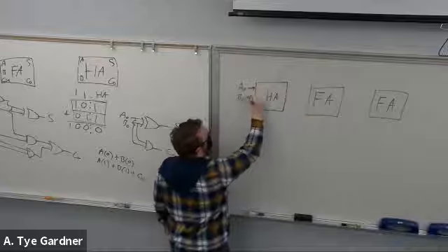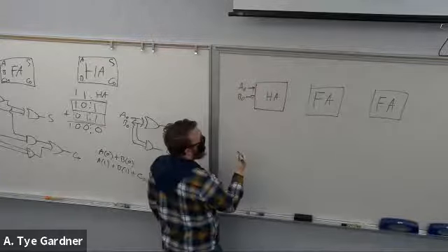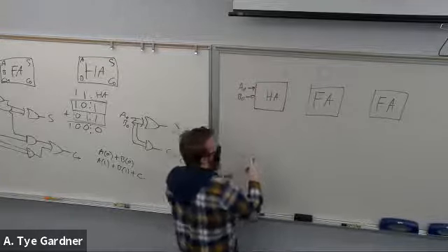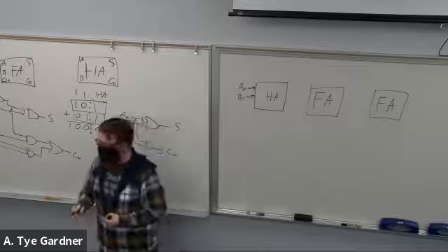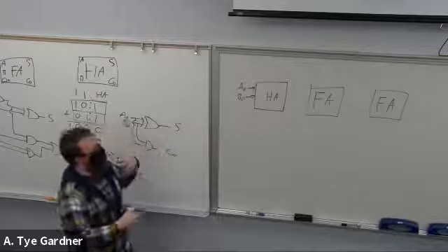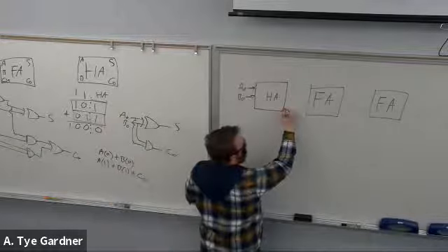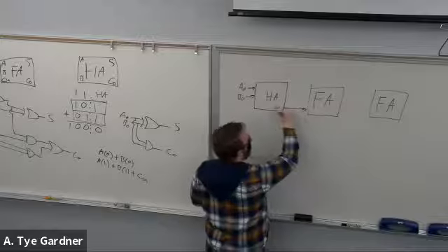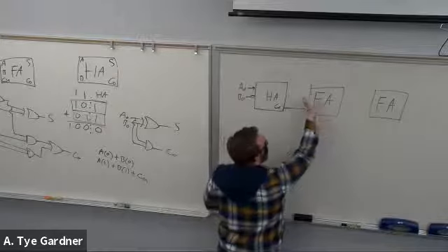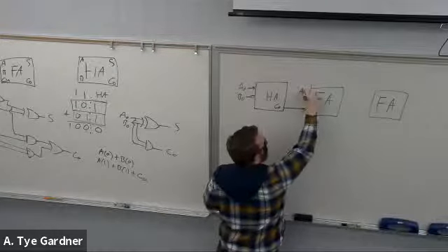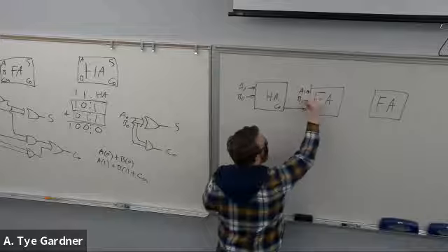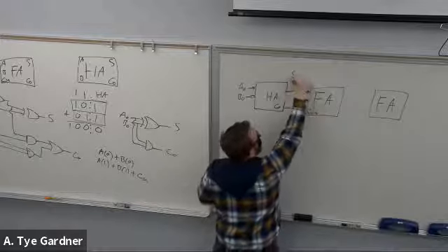So this is what we call the block diagram of a ripple carry adder. So this is where I was going next with this, where it has a carry out that goes to the next one's carry in, and then it has A1, B1, and the sum at 0 we can pull out here.